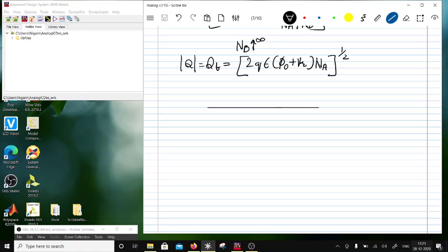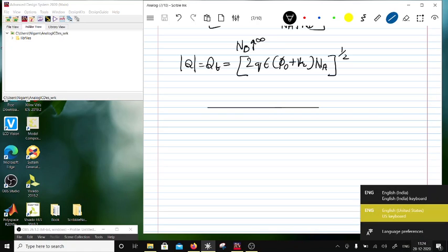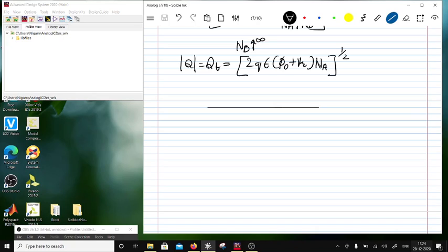Okay, so this MOSFET, this process is an N-well process. So the NMOS device sits directly in the substrate. So when that happens, then what do you have? You have got a gate. The gate is basically polysilicon on silicon dioxide, right? So this is a gate, and the polysilicon is non-conductive, so you implant the top portion of this, and this becomes a conductive poly. So this forms a gate terminal.